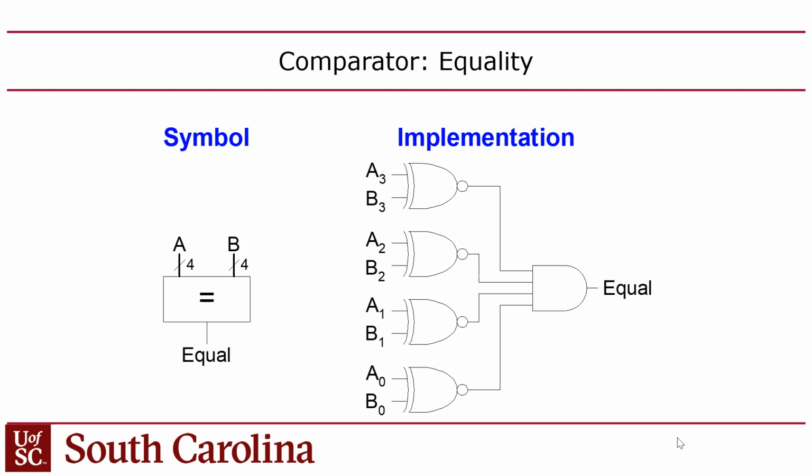Either way, comparisons are pretty expensive because ultimately they involve a reduction where you take a bunch of bits and reduce them all to 1, which involves a fan-in. Fan-ins are expensive. In reality, you will never have a 32-input AND gate. It's impossible. So in practice, if you put this on an FPGA, this AND gate will get split into multiple AND gates staged in multiple stages, probably like a binary tree.